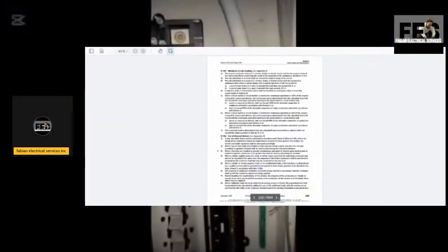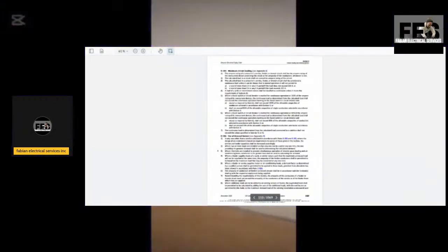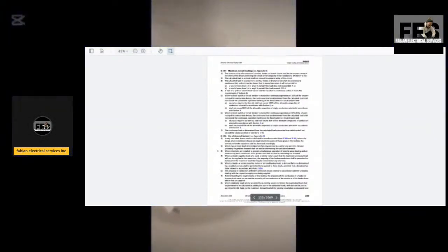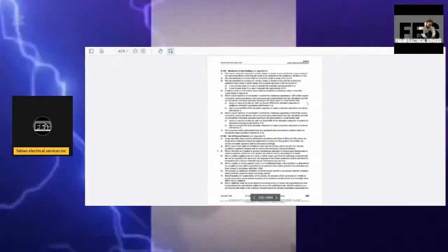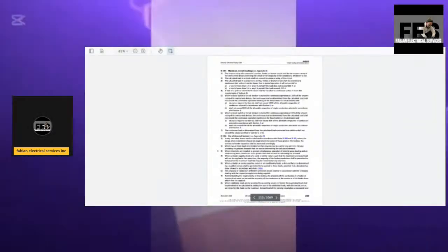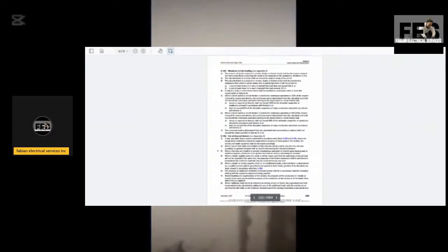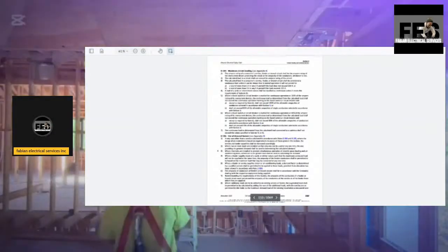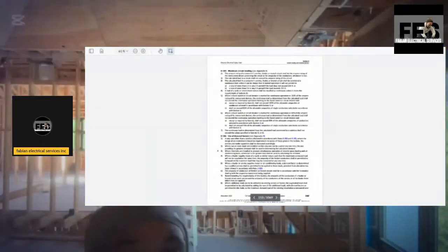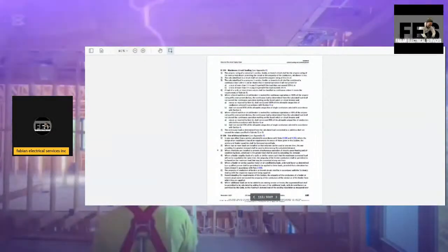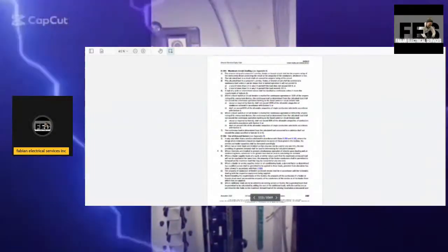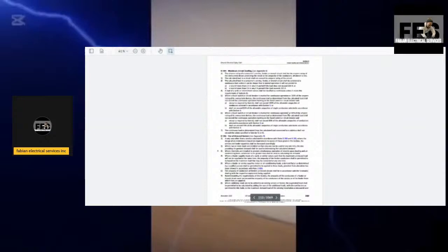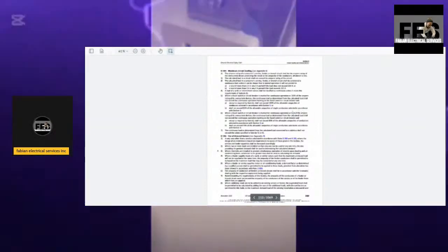When a fuse switch or circuit breaker is marked for continuous operation at 100% of the ampere rating of its overcurrent device, the continuous load as determined from the calculated load shall not exceed the continuous operation marking on the fuse switch or circuit breaker, and except as required by item B, shall not exceed 100% of the allowable ampacity of conductors selected in accordance with section 4, or shall not exceed 85% of the allowable ampacity of a single conductor selected in accordance with section 4.